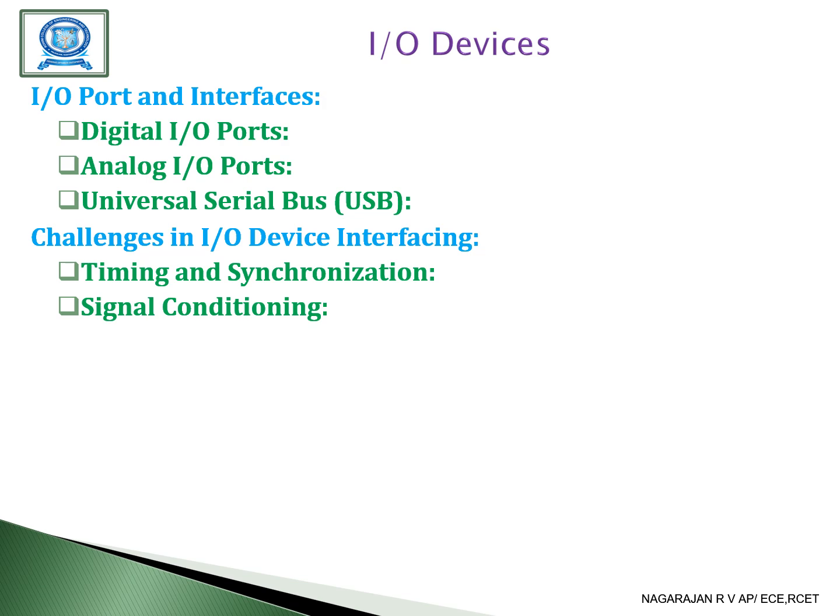Analog signals from sensors may require amplification, filtering or level shifting to be compatible with the input range of the ADC. Next one is noise and interference. Electrical noise can distort signals, leading to errors in data acquisition or control. Shielding, grounding and filtering techniques are often employed to mitigate these issues.